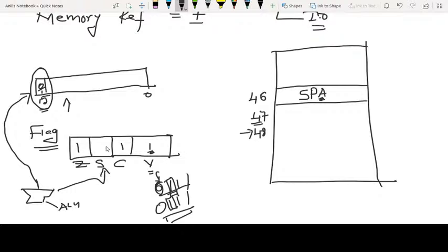But whenever a sign digit has been reversed unnecessarily due to the limitation of the size of the register, then we are in a situation called overflow. Whenever overflow is equal to 1, we reverse the sign digit and set the carry digit. This is how we deal with the sign reversal.